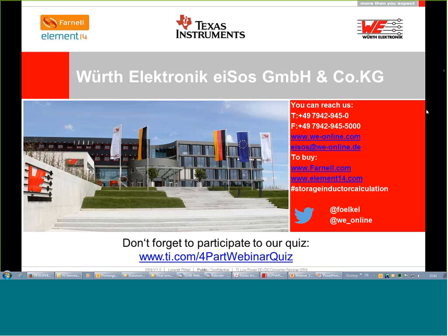Another question: could you list some signs of incorrect inductor issues? Basically, how would I distinguish between an inductor issue and a circuit layout, capacitor, or other problem? Wow, this is quite a wide question. An incorrect inductor choice, I would say, is to use a non-shielded inductor as a DC-DC storage inductor.